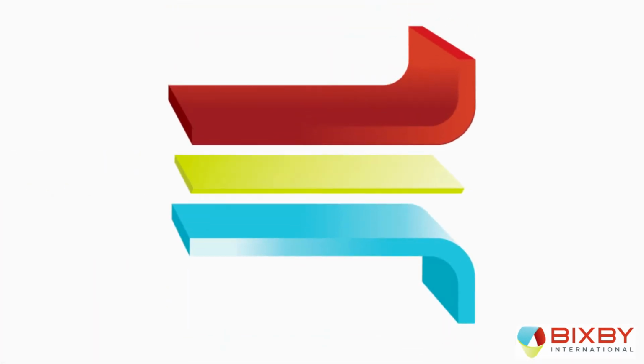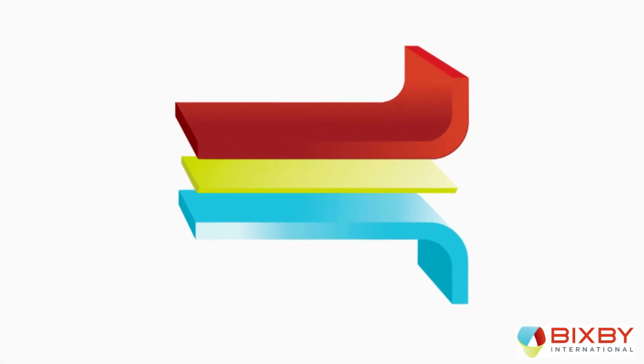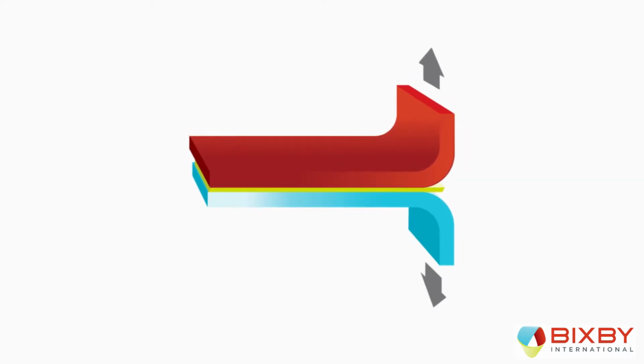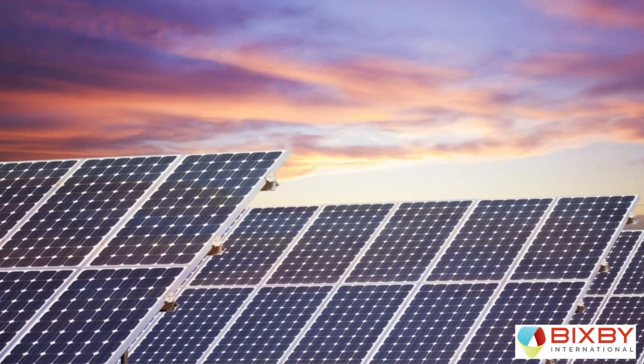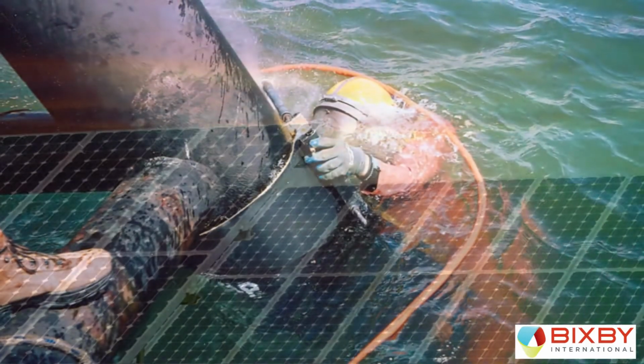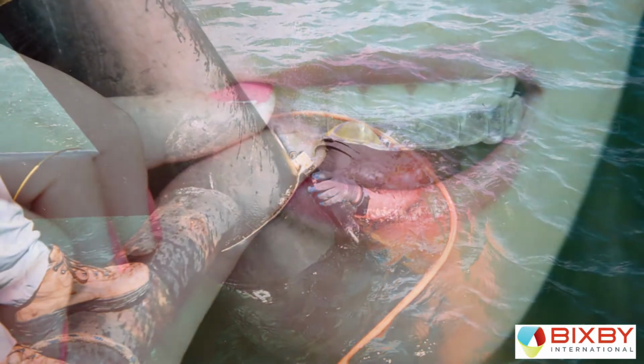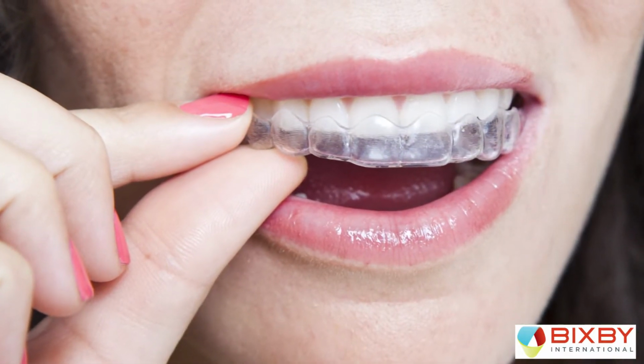The integrity of a laminate bond long-term also can be put at risk by the downstream physical, functional, and environmental requirements of the application. All too often, a bond generated in the lab in a controlled environment is a good, strong bond. But in reality, that bond's exposed to chemicals in the environment, it's exposed to moisture, temperature, sometimes cycling temperature, impact. All of these things really dictate how good your bond is. So while you might get a good bond in the lab, it can fail in months, weeks, even days if it's not engineered for the ultimate end-use environment.